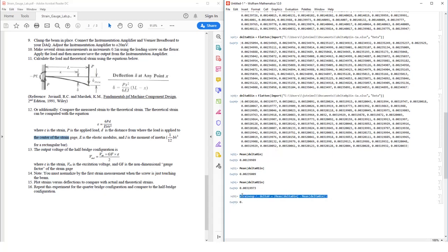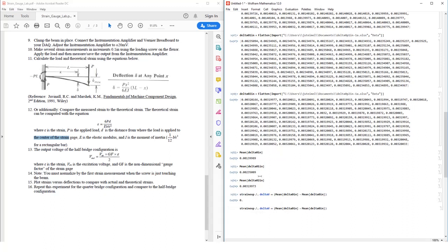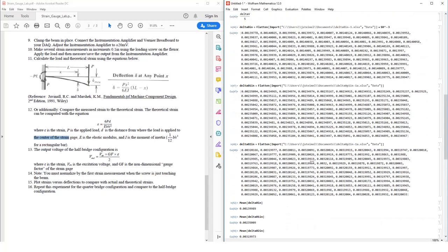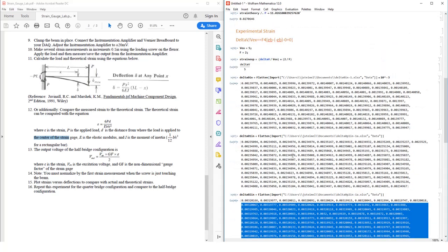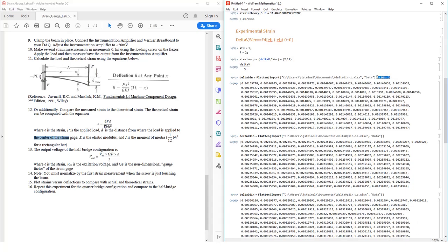That's a good confirmation. If I want to calculate the strain at 0.1, all I do is, again, take my resultant voltage minus that baseline. It's this. And so on and so forth. So that's how you would calculate these values. That's what you want to do in this lab. Remember, these are given already exactly in volts here, so you don't have to multiply by that 10 to the minus 3. You do have to do it, unfortunately, with this first data set. And that should be clear in the lab mathematical notebook.